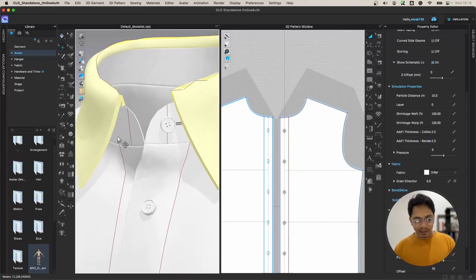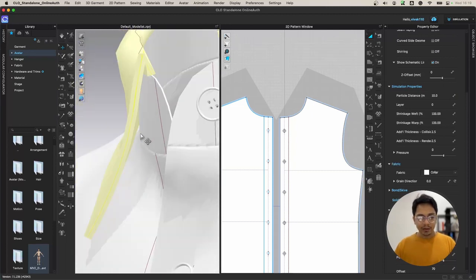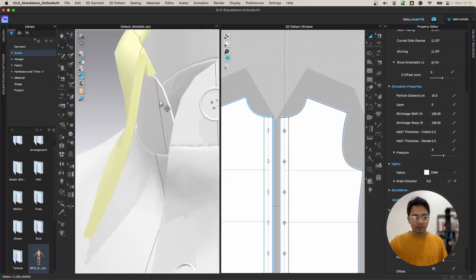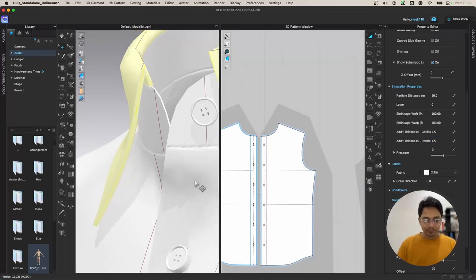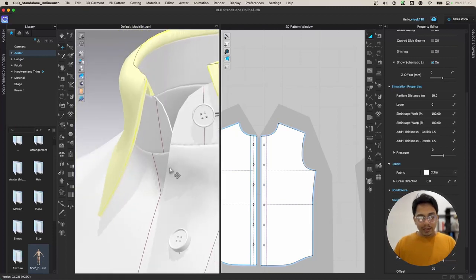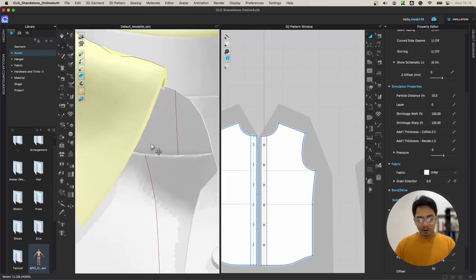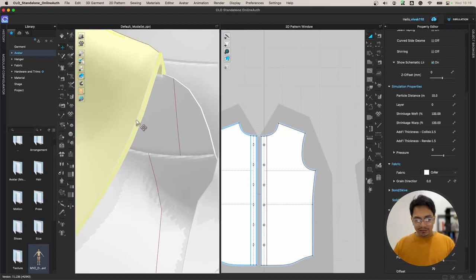Now you see, you have a thickness. This thickness is different, and you can see it has a thickness. Let me try to reduce it a little bit more, 1.5. Yeah, works. Now the next thing I'm going to do: you see the problem here is that the thickness edges are really sharp. So we want to smooth those edges.